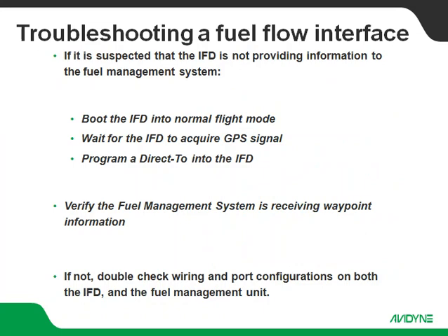And then the other end of it, for all of our fuel flow interfaces, the IFD is providing aviation data out to the fuel flow device. The easiest way to check that out is to boot the IFD in a normal flight mode, wait for the IFD to lock on a GPS, and then program a direct to into the IFD. Just pick a waypoint, doesn't matter.